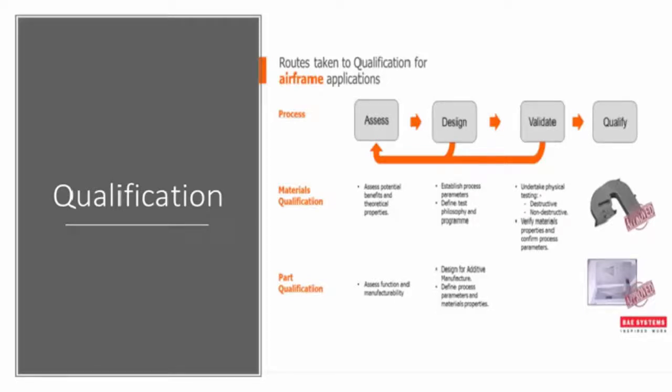For SLM powder bed processes, BAE Systems have qualified parts on a part-by-part basis, based on their functional and structural integrity. Data is still being gathered that will in time form a material specification, but to enable BAE Systems to move forward and harness the technology for low structural items, this was considered an extremely positive way forward.